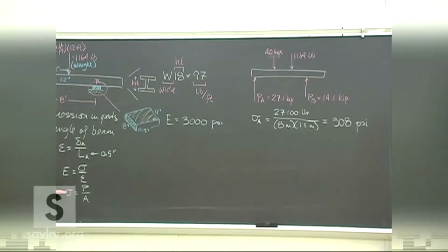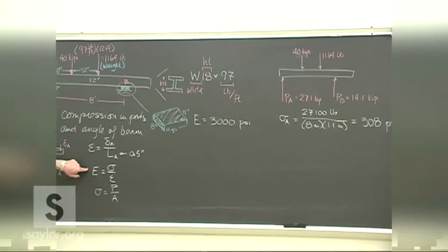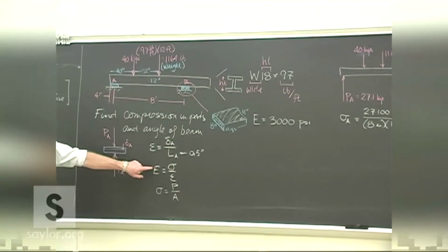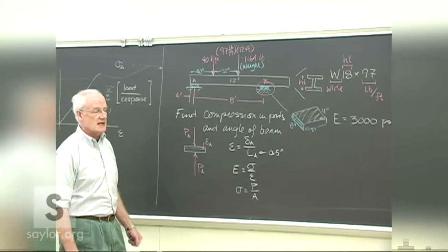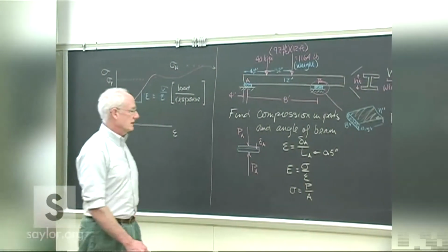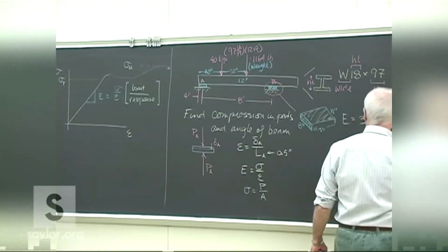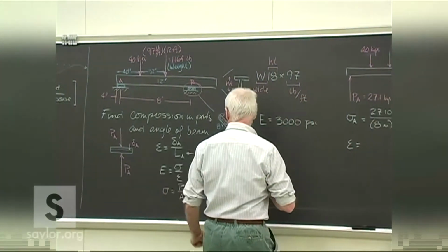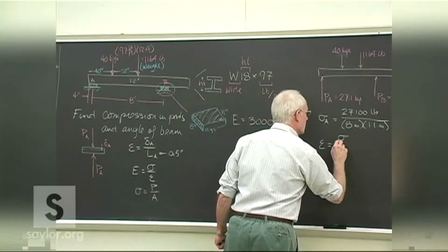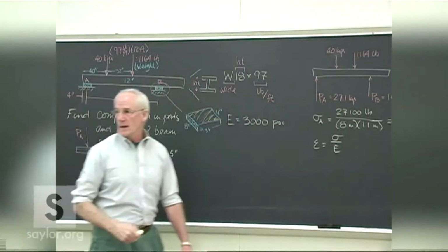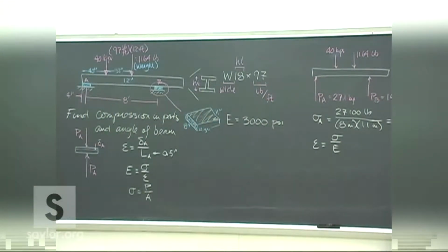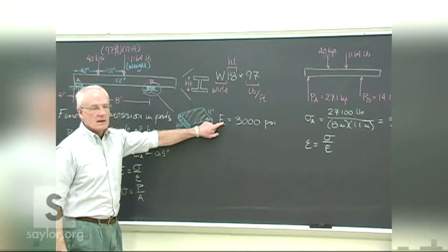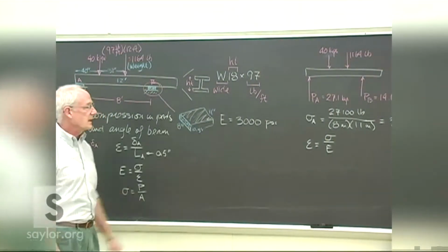So now we know the stress. We're given the modulus of elasticity. Where does that come from? Yeah, that's generally supplied by the manufacturer. You may or may not want that tested, depending upon your level of comfort with what the manufacturer's done. If you have a history with that company, you might trust them. If it's a brand new company, you might want to test a couple of those pads yourself. But that is a material characteristic generally supplied by the manufacturer.